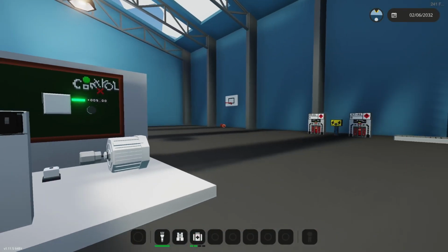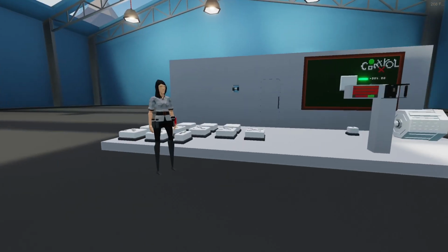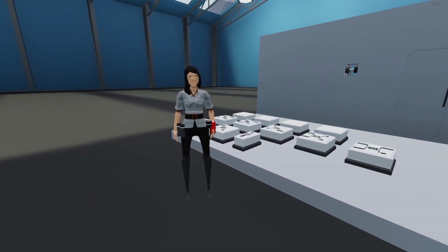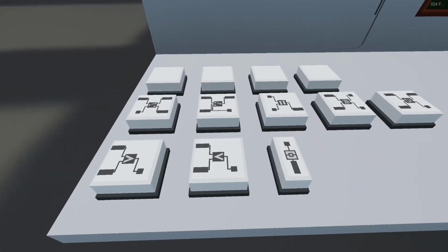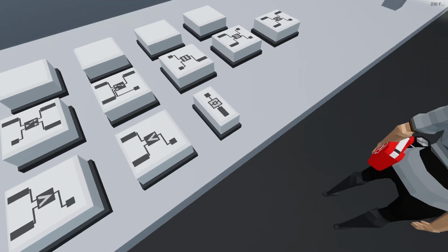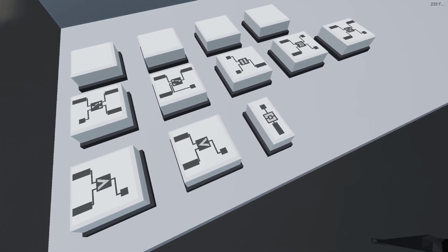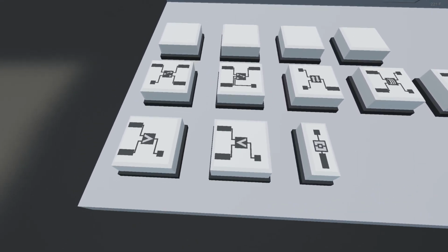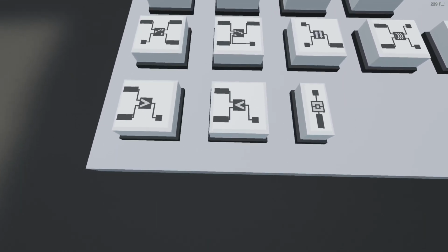Okay, so yes. Whew. Okay, so that was the last bit of logic I was going to cover for this video. Now, quick review, we have back here from the bottom there to the top, we have the greater than, less than, and the threshold gate. They use numerical inputs to test the value against and then put out an on-off signal based on the results of those inputs being compared.